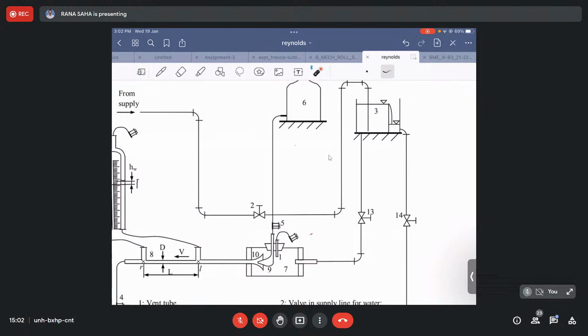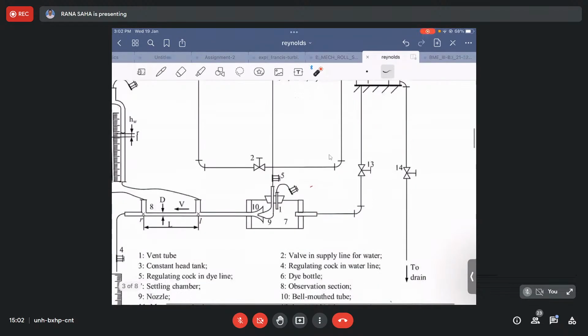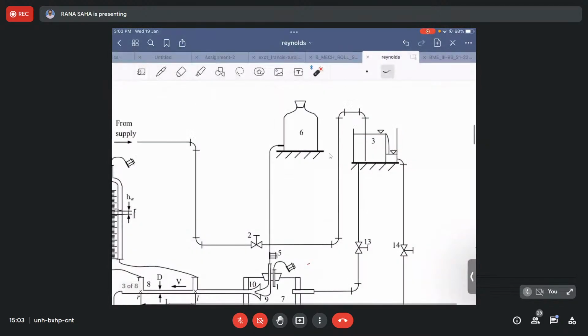If you look into the first chamber, which is being filled by water, the moment this level is achieved, excess water comes here, and through this line it comes out to drain, which is visible to the personnel, or to us actually, that water is coming out from the line. So this indicates that this tank, that means the usable chamber, has constant head. Can we say that?